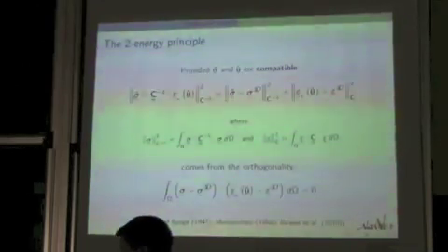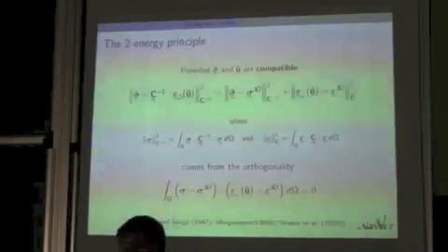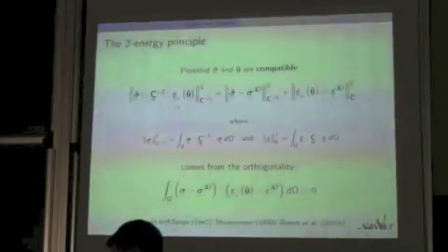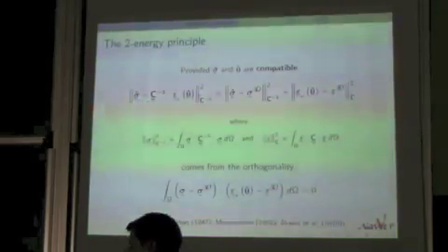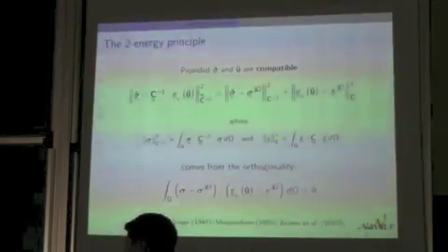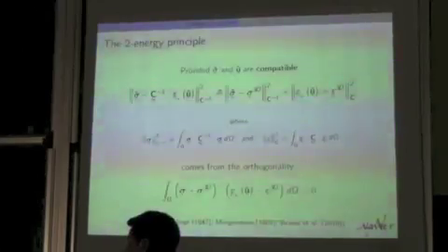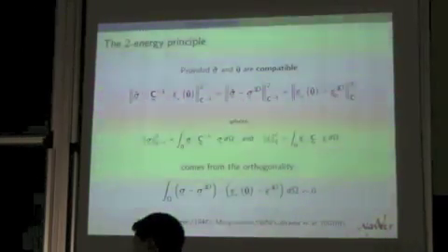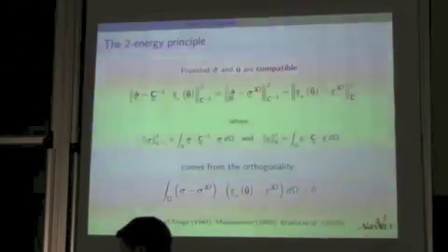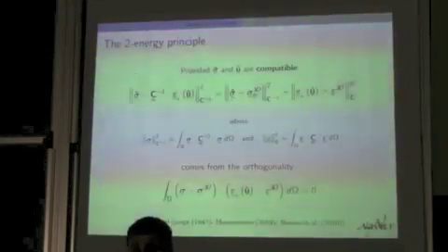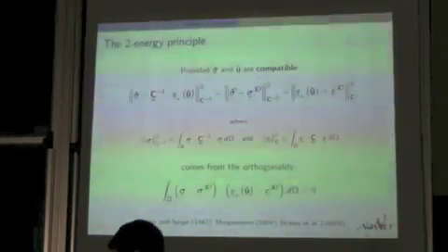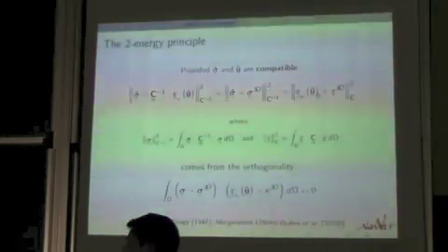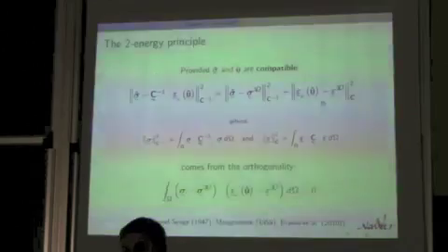If you compute the error between them in terms of constitutive equation, okay, this norm is defined there, it turns out that it is strictly equal to the sum of 2 terms. It's just Pythagoras theorem. It's equal to the sum of the error with respect to the exact solution in terms of stress, plus the error in terms of deformation with respect to the exact solution.